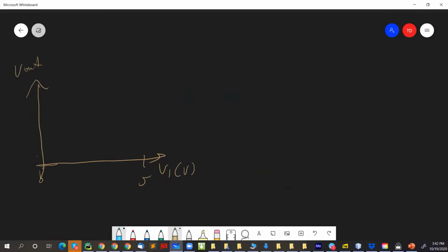Then you're going to set V2 to different voltages. So in the first one, you set V2 to 0.5 volts, and I'm going to sweep V1. What you get when you look at how V out changes is it looks like this. You can see there, very quickly it goes to VDD. So you can see it's got very high gain here. So when V1 becomes greater than V2, then boom, it goes to VDD.